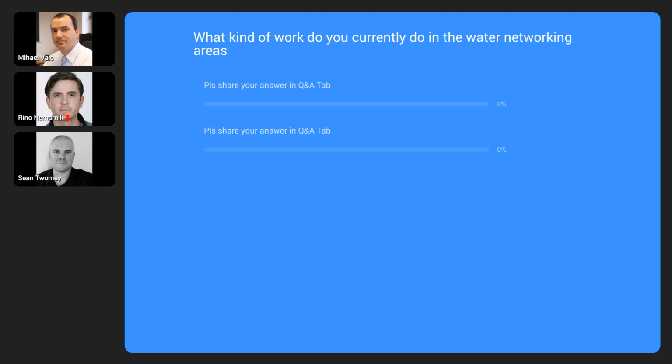And the second, maybe just the question was how does this apply? Well, probably 80 or 90% of the software is the same. So you actually use the same commands to design in layout, design in the profiles, the cross sections. So all of these things are virtually the same. The catalog for the pipes, for the manholes, for the trenches, and so on is the same. And it's the same process to add the pipes, edit pipes in the catalog and so on. So it's always the same workflow.